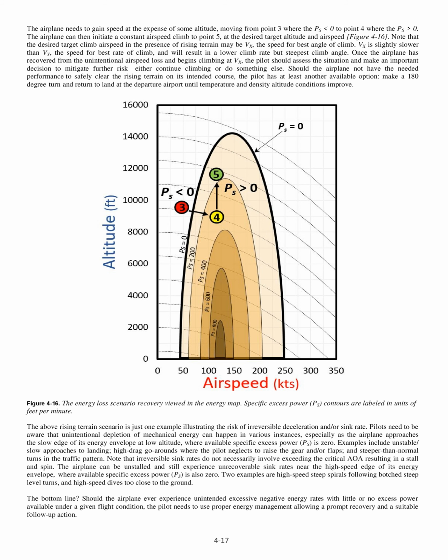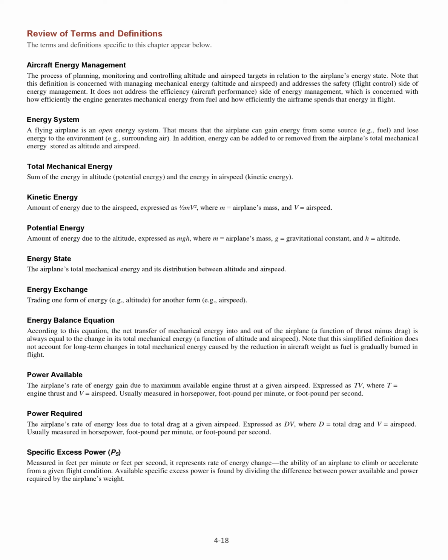The bottom line? Should the airplane ever experience unintended excessive negative energy rates with little or no excess power available under a given flight condition, the pilot needs to use proper energy management, allowing a prompt recovery and a suitable follow-up action. Review of terms and definitions.